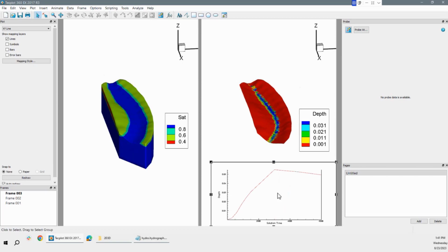And change the size of it and can look here. So you can see here we started at 0, so it was almost completely dry. We have a rainfall event, and the water level went from 0 to about 5.5 centimeters. And at this time, which is about 3,000 seconds, it started going down. The rainfall event ended and it's drying. So by the end of the simulation, we had a water depth of about 4.5 centimeters. Okay.